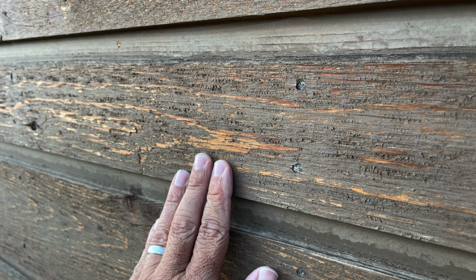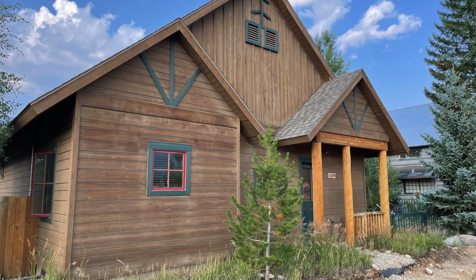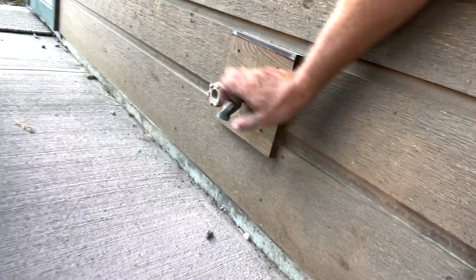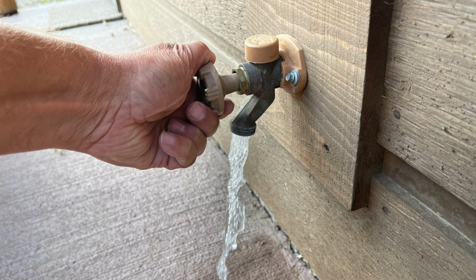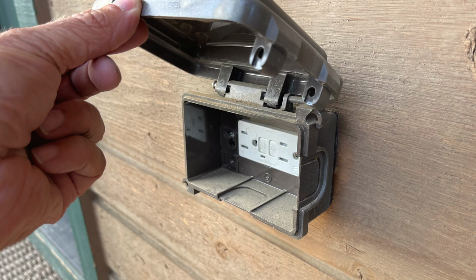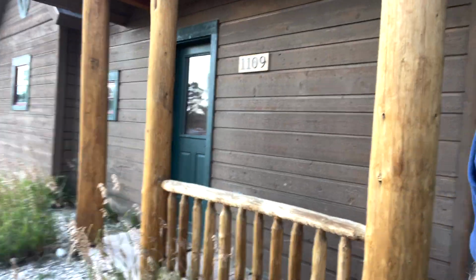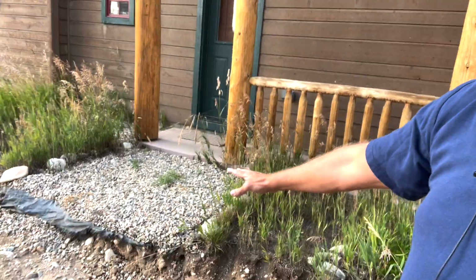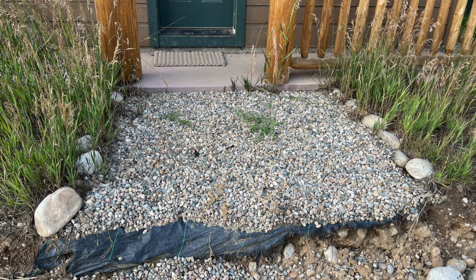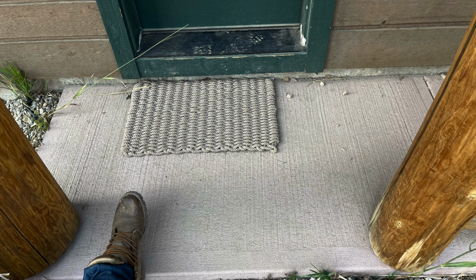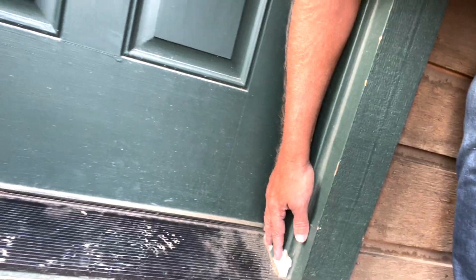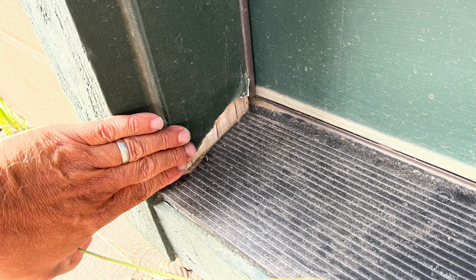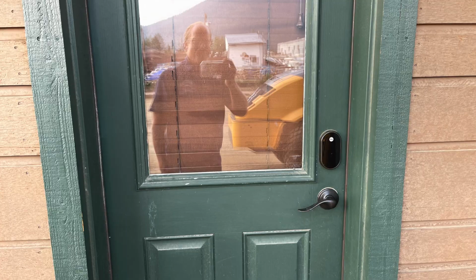Another exhaust hood, and we're at the front here with a water faucet, frost-free hose bib, the running water, an electric receptacle, GFCI. I'll test that. And again, unfinished work at the front step, and some minor paint at the exterior door here. This door is not 3 feet wide. It's not the main egress door. You need one egress door that meets building code.